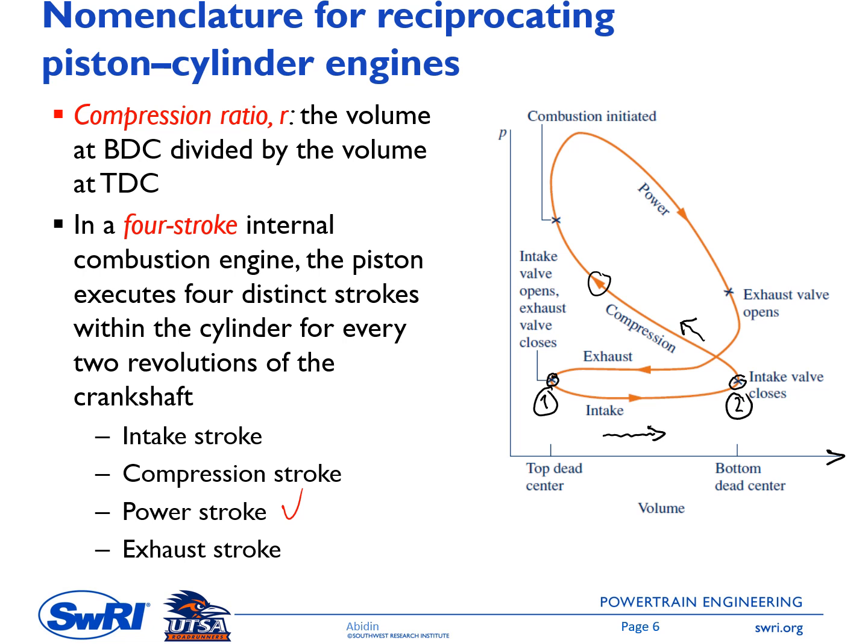or the fuel will be injected inside the cylinder chamber for the diesel case. So let's say this is the timing for the spark ignition or the timing for the fuel injection. We have combustion initiation at this point, and then there will be a combustion process inside the combustion chamber. The pressure and temperature increase. So here you can see the increase of pressure, and then the piston moves down again toward the